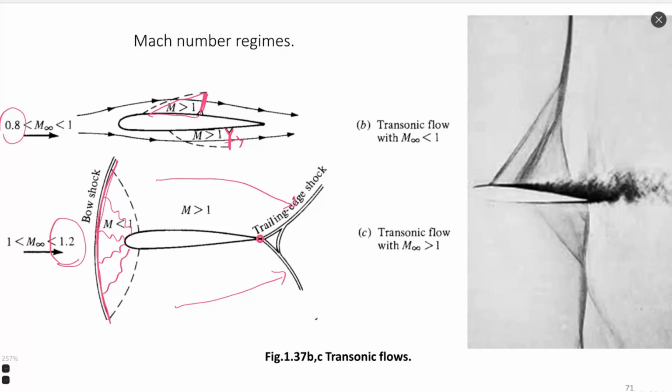You can see visualization by Schlieren photos of shock waves, or lambda shock waves, which are connected to the airfoil and also related to flow separation. A big shock wave is generated by several smaller, weaker shock waves.